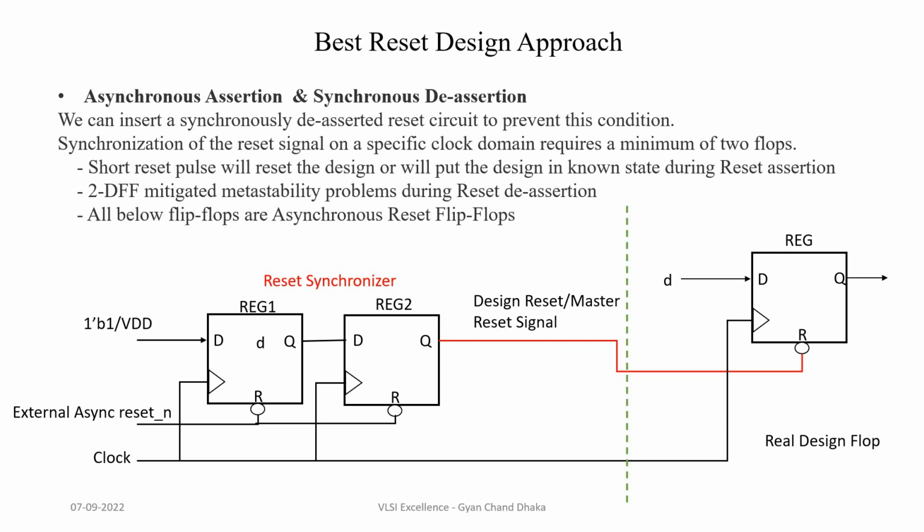After power off, every design wants to be in a stable, known state. So the reset is expected to be asynchronous, applied to all of the design's flip-flops, so the design gets to a known state.